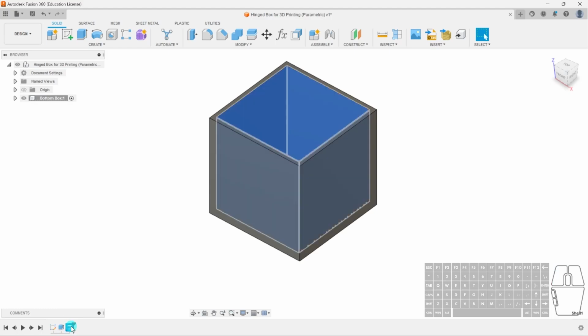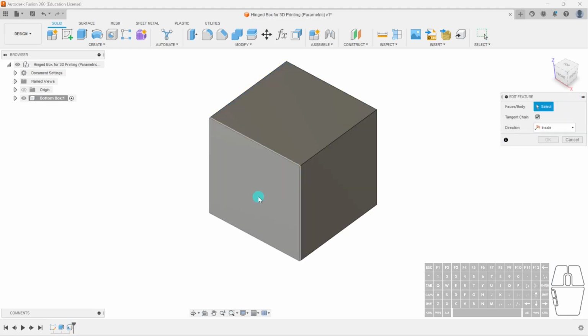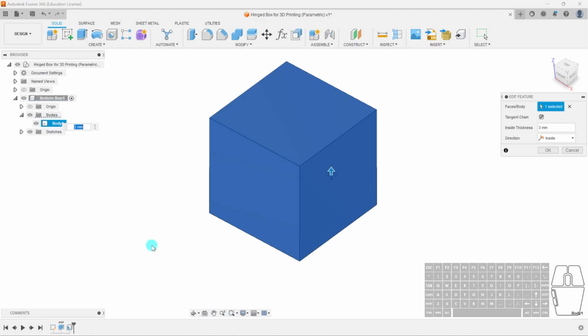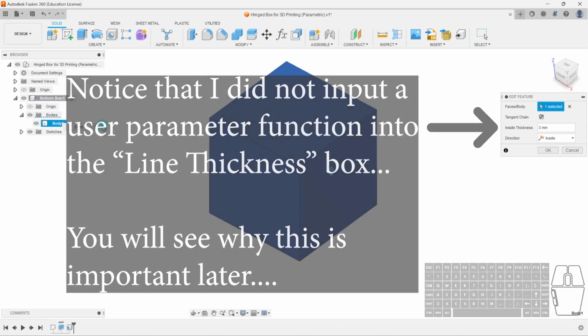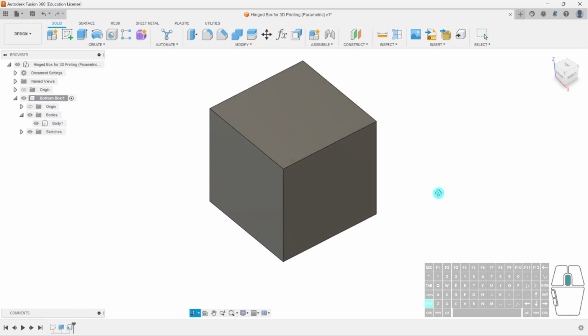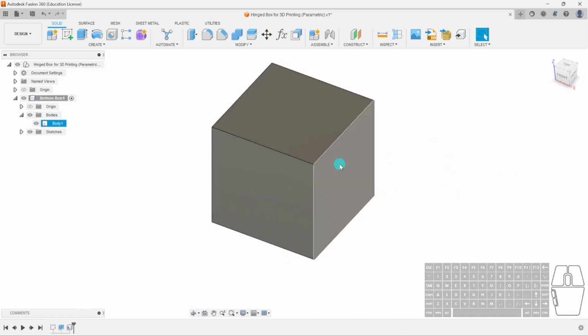So what you can do is instead of selecting your face, you can select the entire body, right? So I'll drop down here in the drop down menu, bodies, and I can select the entire body. Alternatively, you can also select each face or side of your cube. It's a lot simpler to just select the body, so I'm going to select the body. I'll hit OK. And now you can see I've still got my cube, there's no face missing.